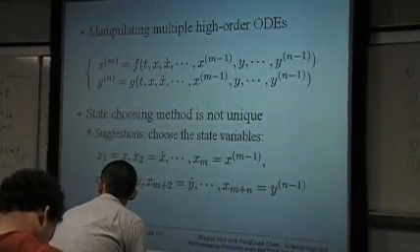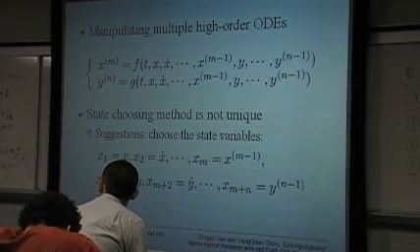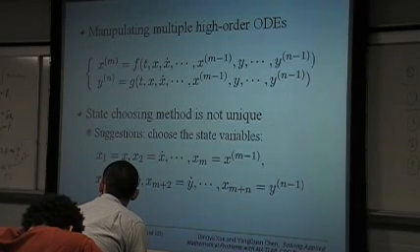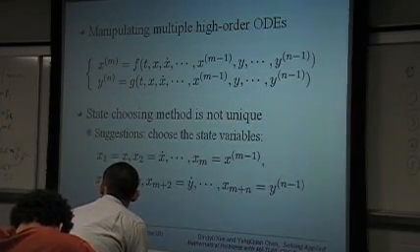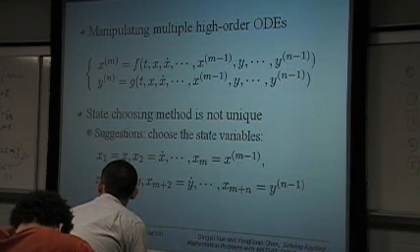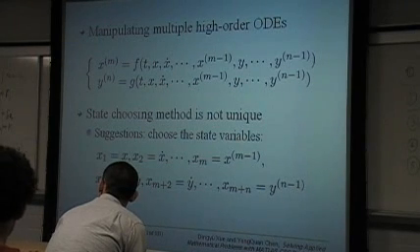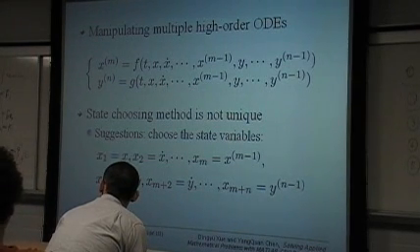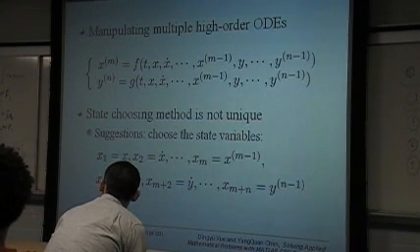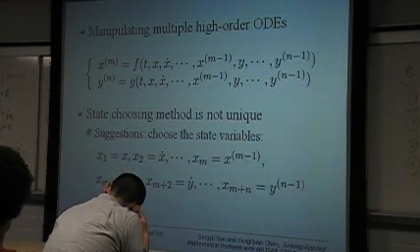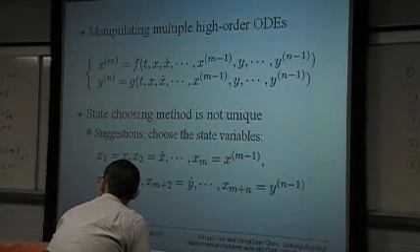Epsilon equals 10 to the power of minus 3. It is a very large value. It is equivalent to 0.1% of error, so it is too large for numerical computations. Normally we will select a very small number, and then we can have better control of the intermediate result and finally the result of simulation.